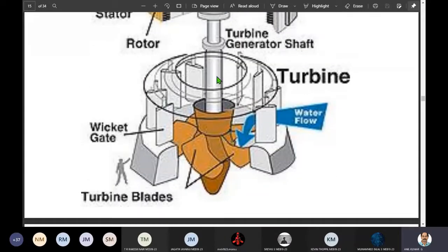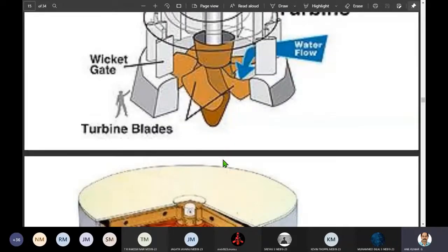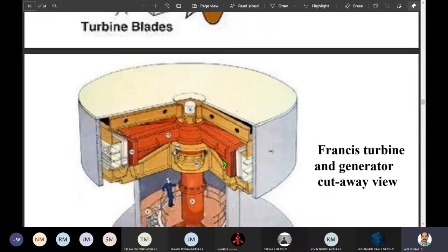And you have the turbine runner fixed vertically, and the water will be entering, like this. And these are the wicket gates. What is written here is stationary vanes which will guide water, but it is in reaction turbine runners. So this is an axial flow Kaplan runner, in fact. So we'll understand when we study this clearly. Axial flow reaction turbine. Radial flow or mixed flow reaction turbine is the Francis turbine.